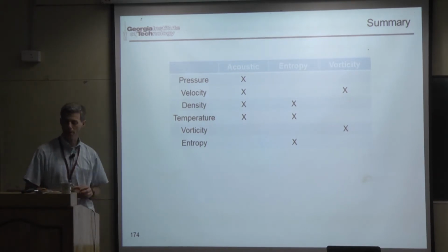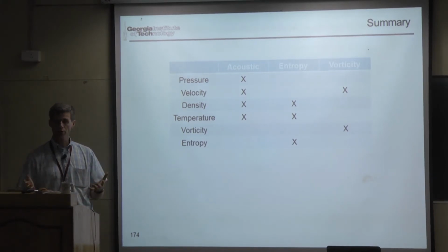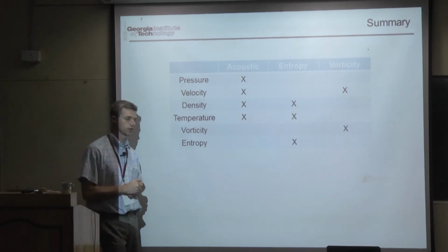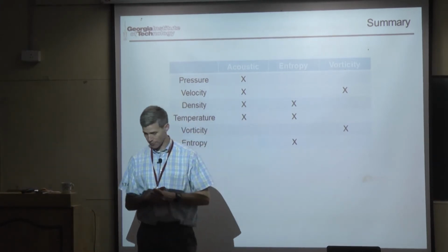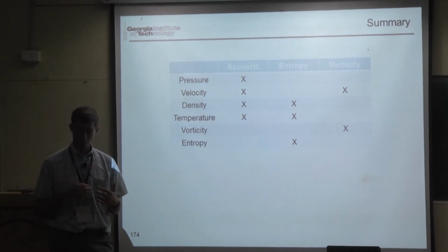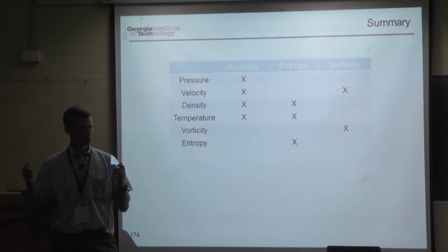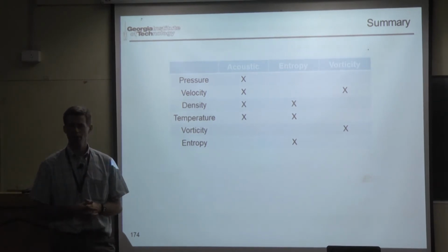But there's also another property about them. The acoustic disturbances in a low Mach number flow, the structure of the acoustic field is relatively insensitive to the details of the velocity field. So you could have 10 different combustors with 10 completely different flow fields. As long as the Mach number is low, you could have essentially virtually the identical acoustic field. Same natural frequency, same modal structure of nodes and antinodes of the pressure and velocity field. If you were to make a measurement, take a microphone and map out the pressure field, 10 combustors, 10 totally different flow fields, essentially identical pressure fields.